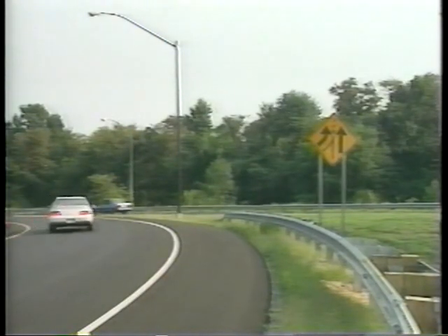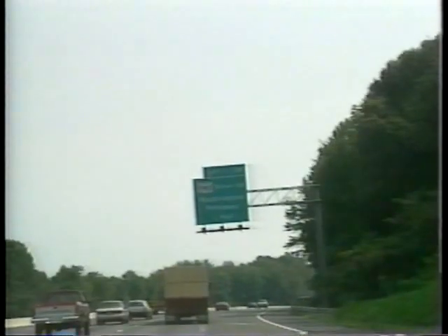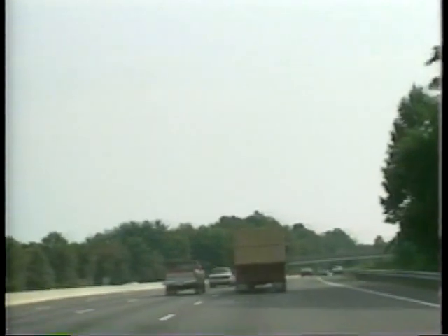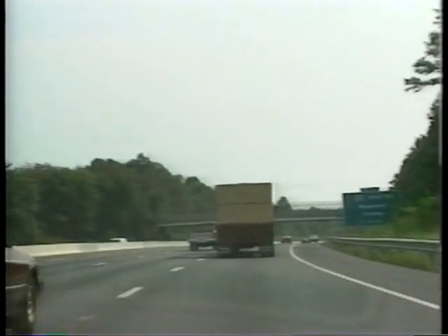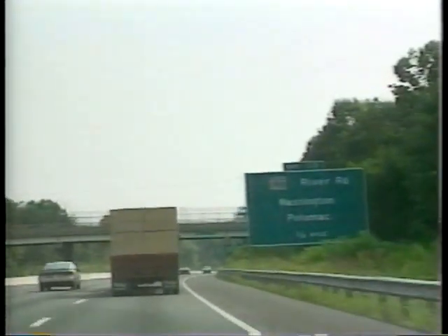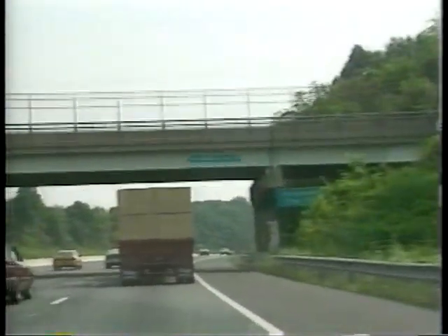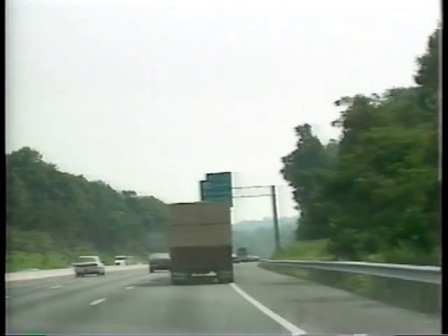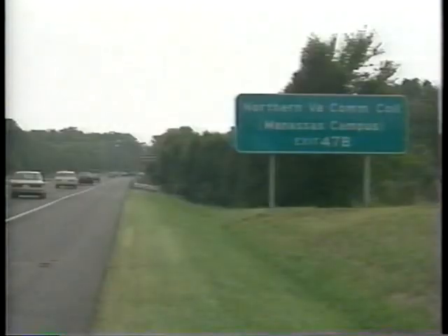Exit numbering should be sequential and based on milepost numbers. Signs at interchange approaches include merge signs and advance guide signs. For major and intermediate interchanges, 2 and preferably 3 advance guide signs should be used. They should be put 300, 600, and 1200 meters before the exit. This placement allows the driver to make complex decisions regarding which route to take.